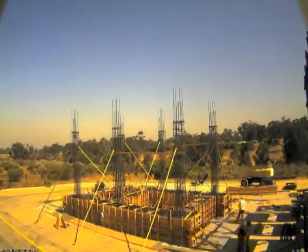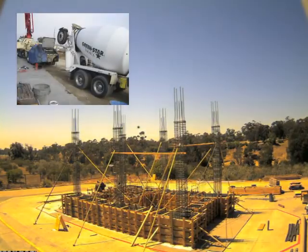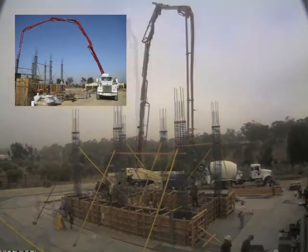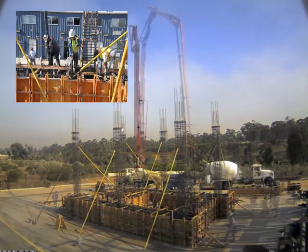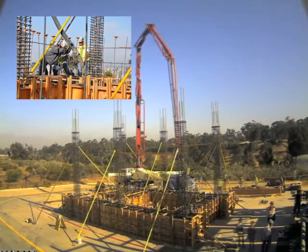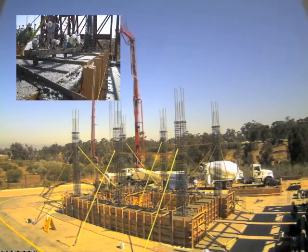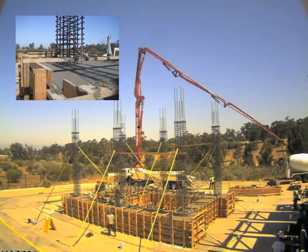Once the rebar cages and formwork are completed, the foundation concrete is poured. In this project, the concrete was poured using a truck-mounted boom pump method. Concrete can be used in two forms, precast and cast in place. As the names offer, the precast concrete products are built off-site and then transported to the construction site, while cast-in-place concrete products are built at the spot where they're supposed to be located. In this project, the concrete is poured and hardened on the site, and therefore the cast-in-place method is used.